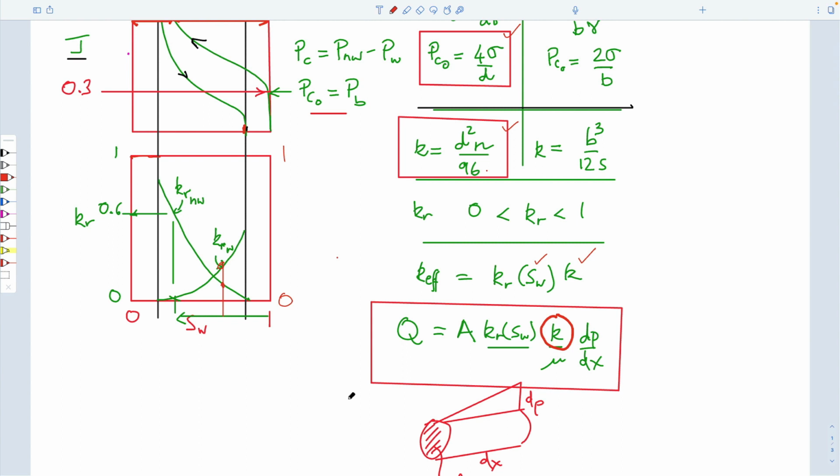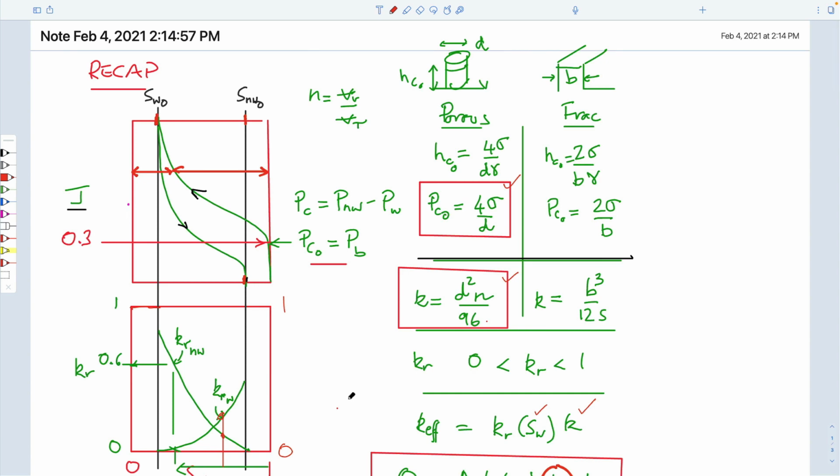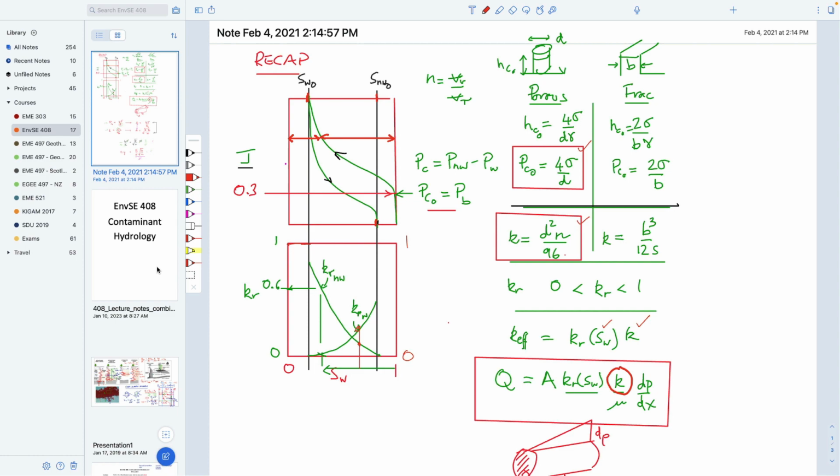And then last time we talked about practical applications of why exactly these materials in situ have this residual chimney, a puddle which might be buoyed up on the water table for LNAPLs, and that might be a residual chimney in the vadose zone going all the way through the groundwater zone and being buoyed up on a capillary barrier for DNAPLs. And so we explained all of that in terms of our understanding of these fundamental behaviors.